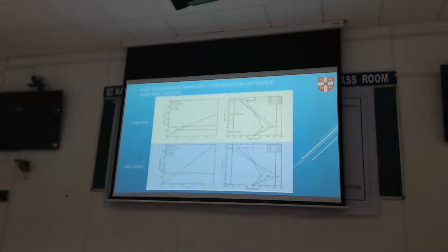And this is slightly how the bending moments are changing with depth. So I'll get big things there on the positive, on the negative side, and the positive bending at the interface between the liquefiable and bearing layer. This is more conventional. We understand this more easily. So the more deflection I'm allowing the pile to undergo, the more bending moment I get because my curvature increases.